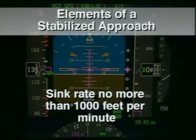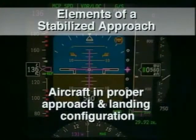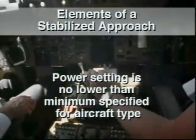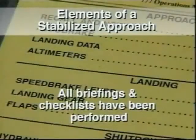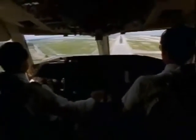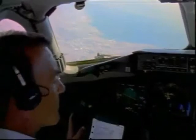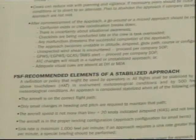Sink rate is no more than 1,000 feet per minute. The aircraft is in proper approach and landing configuration. Power setting is no lower than the minimum specified for the type of aircraft, and all briefings and checklists have been performed. All of these approach parameters must be met by 500 feet, including visual approaches. If your standard operating procedures do not include parameters for a stabilized approach, the Flight Safety Foundation recommends that you use the parameters just listed.